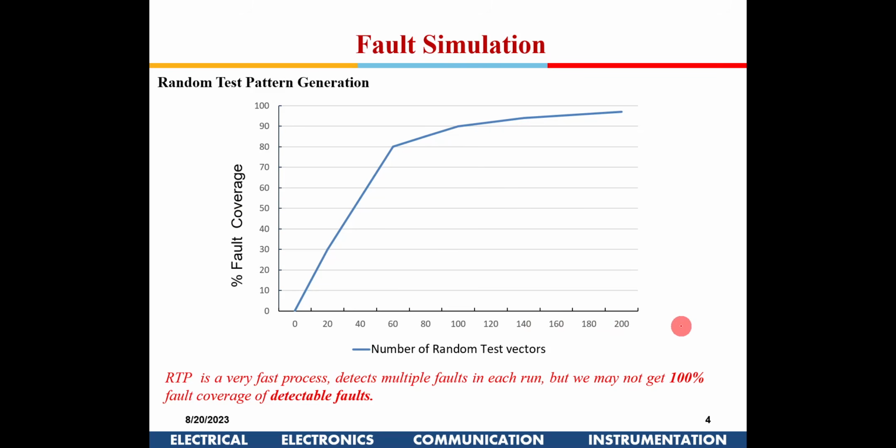techniques soon, but before that there is something known as random test pattern generation. Suppose it's a 3 input circuit, we don't start with 0 0 0, then 0 0 1, such sequential testing from 0 increasing the value by 1, that is not resorted to. Generally, if you have n number of inputs, there will be some random test pattern generator.